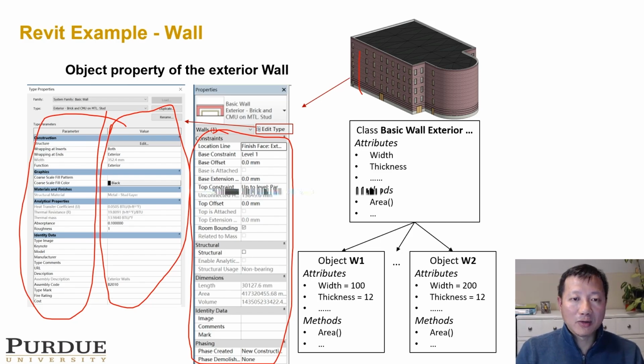This is also a good time to remind you that whenever your intention is to just make changes to the objects in your own Revit project, make sure you use this duplicate button. Otherwise, if you don't use this duplicate and give your type or class a new name, all the changes you apply here will be stored in the system. And in other Revit projects, when people have this type, their attribute values will get changed as well. So be careful about that part.